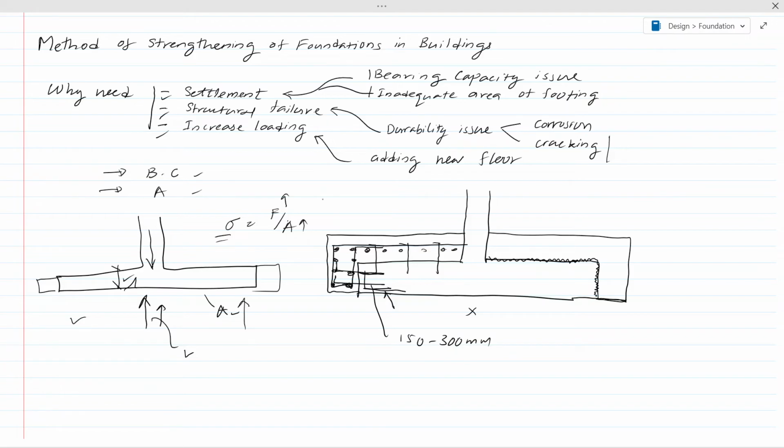So we have several things to consider as we discussed. If I summarize, first one is the dowels. Now you have to put the dowels, then you have to do the roughening, right? Then you have to apply the bonding agent on this surface before concreting. The time of application could depend on the product, so you have to check with the product, but you have to apply bonding agent along this surface. You should apply that, because it will enhance the bonding in the connection. Then you can do the concreting of this part.